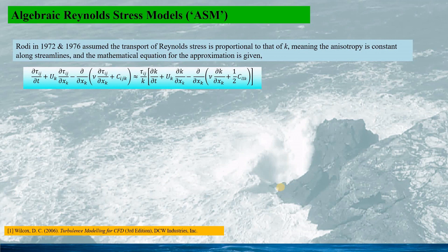They can be applied only together with the 2-equation turbulence models, for which the turbulent kinetic energy k and the dissipation rate epsilon are available. As such, in turbulent flow modeling, the computation would be slightly more than the conventional 2-equation models, but would be significantly less than the Reynolds stress model, the 7-equation turbulence model.